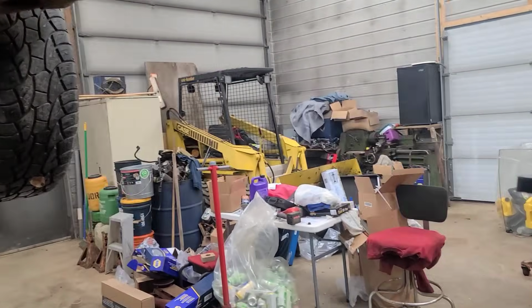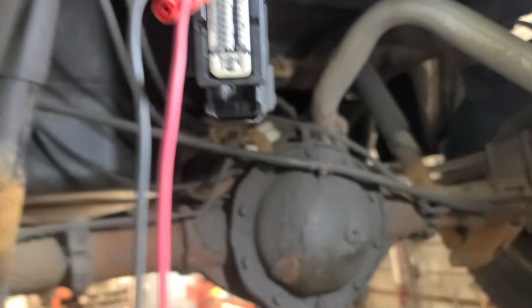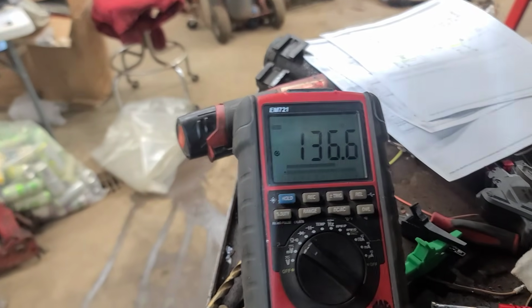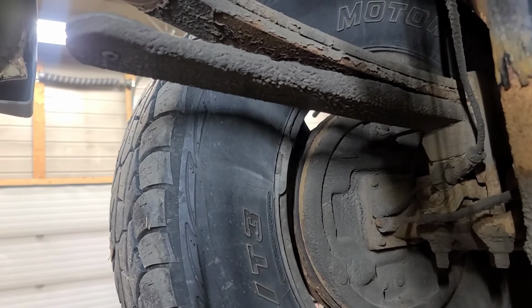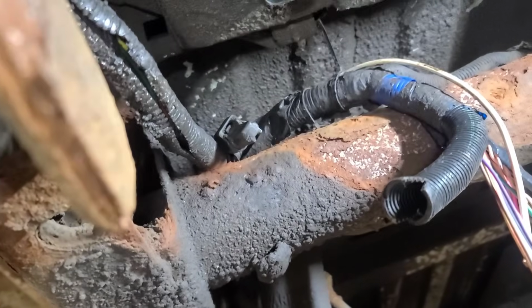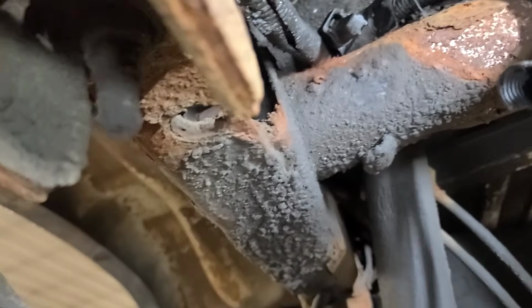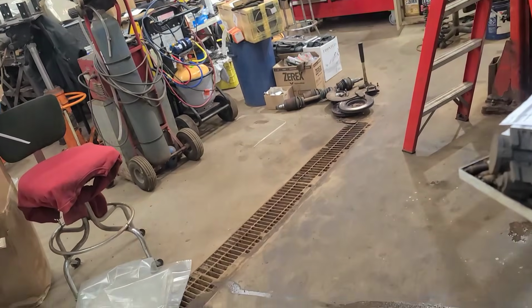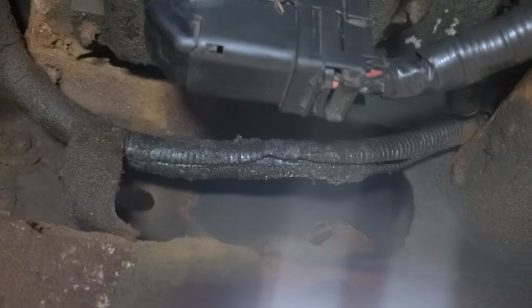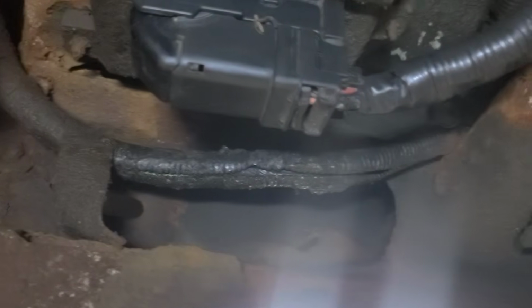So let's plug this ABS module in. So I've got the ohm meter plugged in, I got the ABS module plugged in, I'm reading 136, which is a bit high, but it's definitely not open. So let's plug this fuel pump driver module back in. Cleaned all the excess dielectric grease out of it. And see what we see up top. I had to change the seal inside there because it was swollen and I couldn't get the connector to latch correctly. But it's in there now.